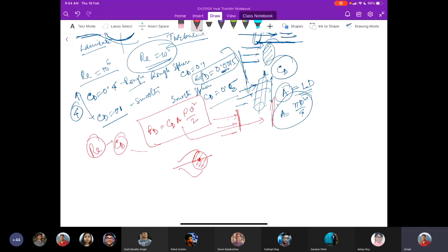Now, depending on the value of Reynolds number, because this influences the velocity at which the flow is approaching the object. As we have discussed, at theta of 80° for laminar boundary layer, flow separation happens. Similarly, the local Nusselt number around the periphery, which is varying with theta, reaches a minimum at this angle.